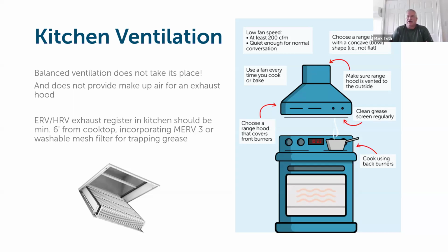But if it's a very tight house, I would say any kitchen exhaust hood needs some type of makeup air. We do offer heated makeup air for kitchen exhaust applications. It's very important.